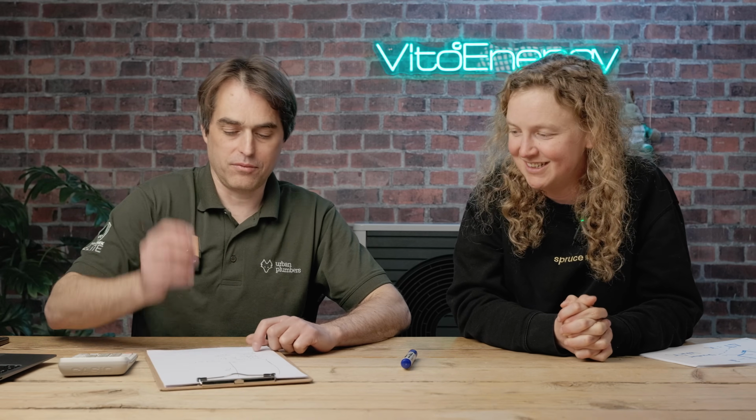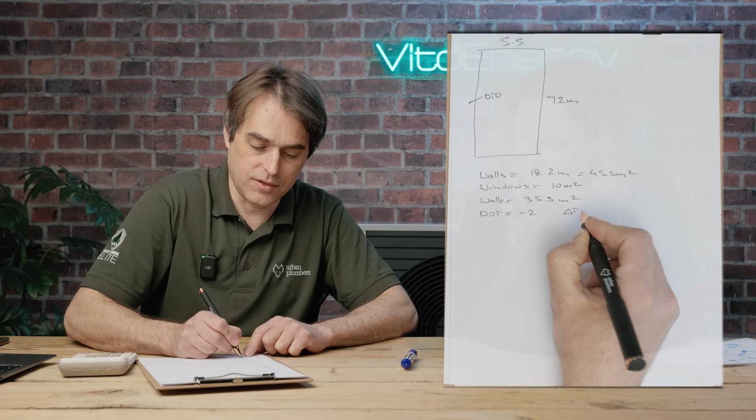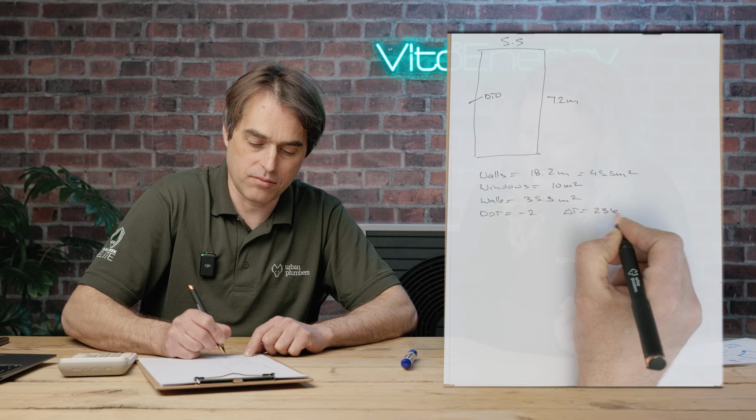It's an office, 21 degrees inside. Nice. What's the design temperature here? -3, -2. How do I know that? Yeah, good question. So you would look that up in the CIBSE design guide for the nearest location. You'd correct it for altitude if this was a funny altitude. This office is probably not at a very funny altitude. I actually haven't checked it, but let's go with -2. Keeps our maths. So -2, 21. We've got a DT of 23.